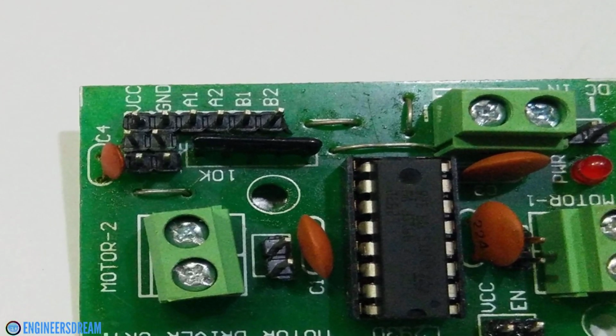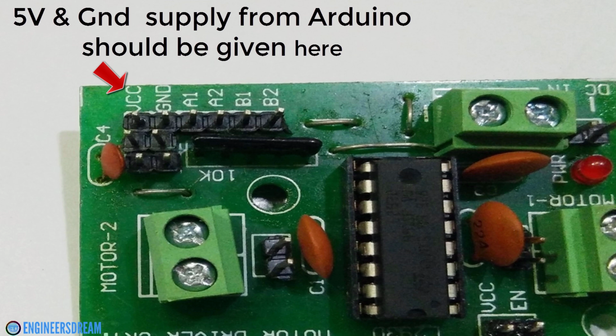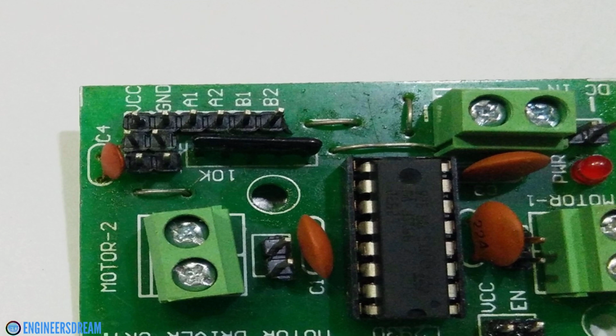Now, if we look closely, then there are 2 more pins for VCC and ground. So, at the VCC pin, we had to provide a supply of 5 volts from the Arduino. That is, I had to supply power from the 5 volt pin of the Arduino to this VCC pin. And I also had to connect 1 ground pin to the ground pin of the motor driver. So guys, the disadvantage that I found of using this motor driver is that I also had to give 5 volts of supply from my Arduino to the VCC pin of this motor driver.